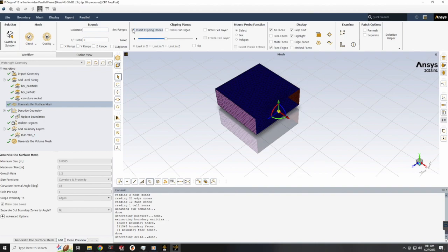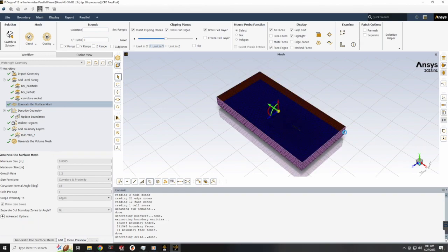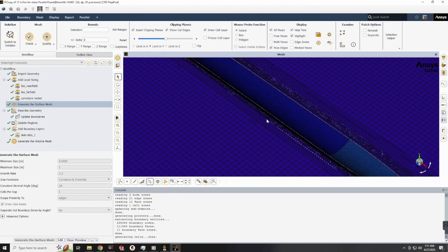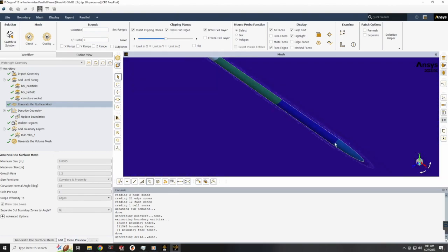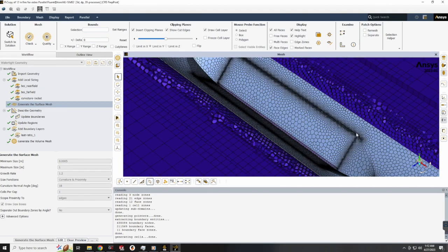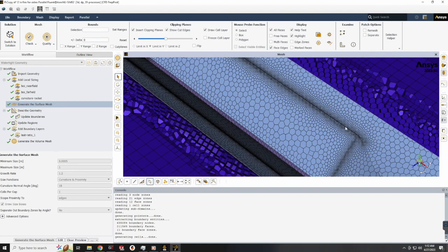And then this block right here generates the surface mesh, and the surface mesh already exists. But we can look inside this thing. So here's the mesh in here, what it would have generated. You can see this is up by the nose cone, and this is the tail cone of the rocket. And this is sort of looking at one of the fin mounts from the inside. You can see down here where there's sharp corners, there's cells as small as 0.5 millimeter.